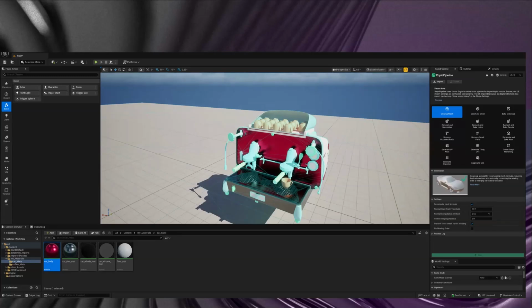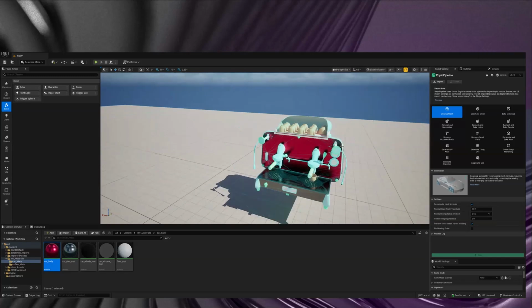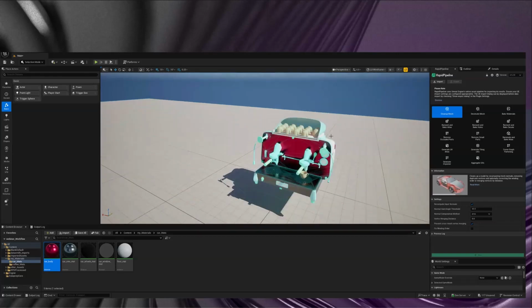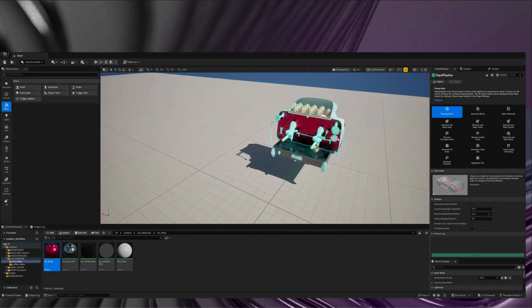Basically, they were asking, why would we use this tool if I'm a freelance 3D artist and I need to present stuff to clients? And I was saying, if you have any complex 3D assets that you need to optimize to work in a real-time way, then that's the basic answer. And CAD is a common problem there because it's usually badly tessellated. It's got too much detail in certain areas. It's got tiny little parts that you don't need that slow things down. So there's a whole bunch of things. And if you're using Unreal, well, it's all based around real-time rendering, and that has limits. So this kind of helps you solve those limits, basically fix things up.